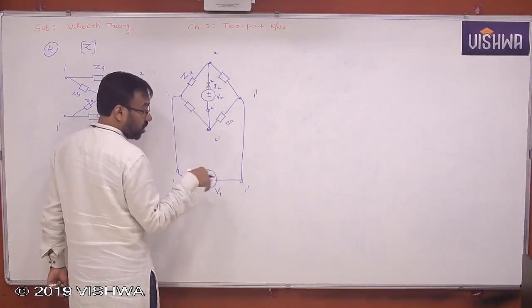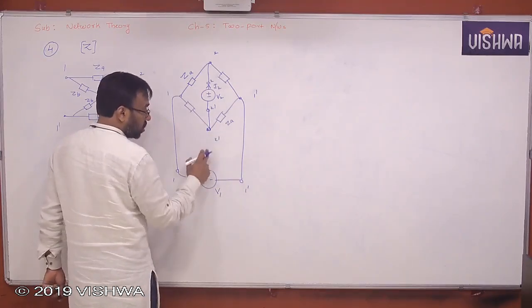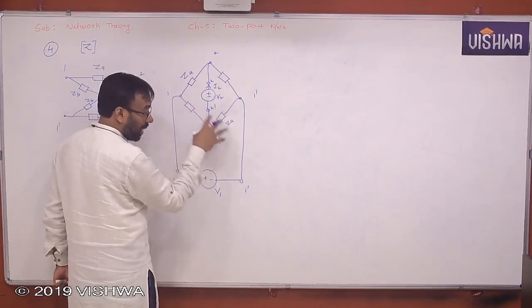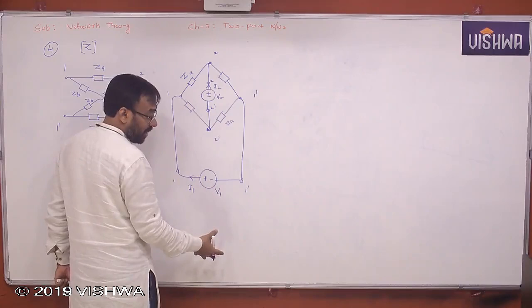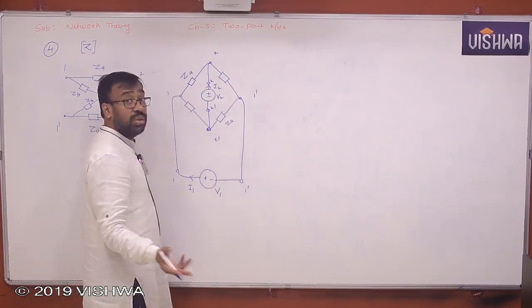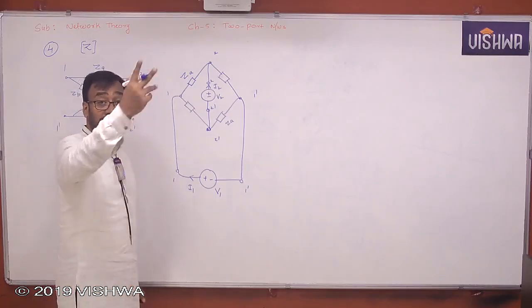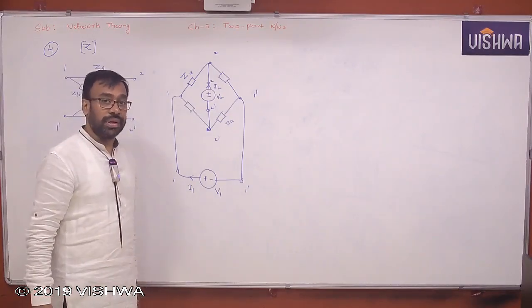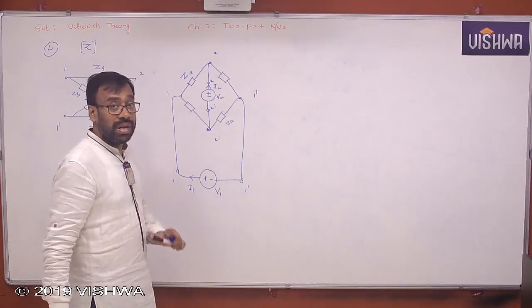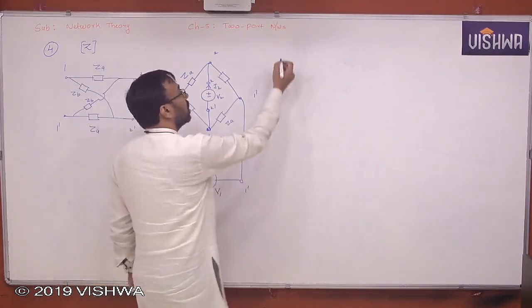Now let us apply either mesh analysis or else conditions or definitions. The first method says you apply definitions or conditions. So these are the 3 loops. In those 3 loops, if you apply KVL, get some equations and remove the unwanted variable, then you will get the resulting equations. Those resulting equations can be compared with the standard equations of the Z parameters. But I'm not really preferring that method. I can do that, but I'm preferring the conditions. So conditions are definitions.